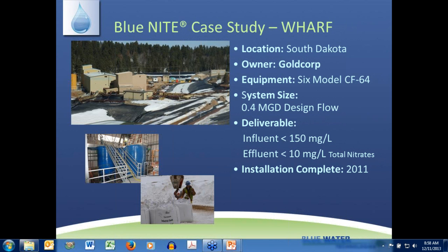Most of the time in the FGD applications that I've seen, if we're still on that thread, I noticed that the nitrates are much lower than this application. I would say more in the range from 30 to 70 milligrams per liter. And the lower they are, the less detention time you need for complete conversion.